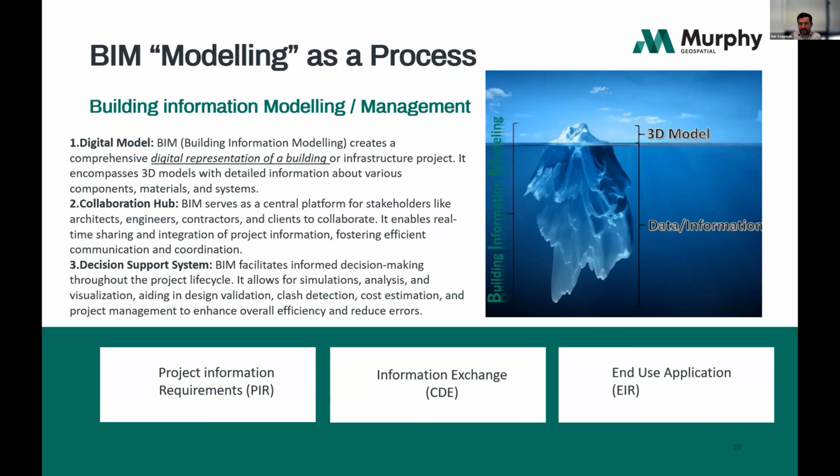By starting with the end in sight and following the processes defined by the BIM standards, and ISO is the main one, more value can be gained from BIM. We're often asked for a scan to BIM 3D model, but we follow ISO 19650 when we drill down to the PIR, the CDE, and the EIR to get better use from the end-use application. Many of our clients say, "Oh, just give us a model." So you're paying for this additional service that you could be getting better value for, bringing that model all the way through from conceptual stage one into design, handover and asset use.